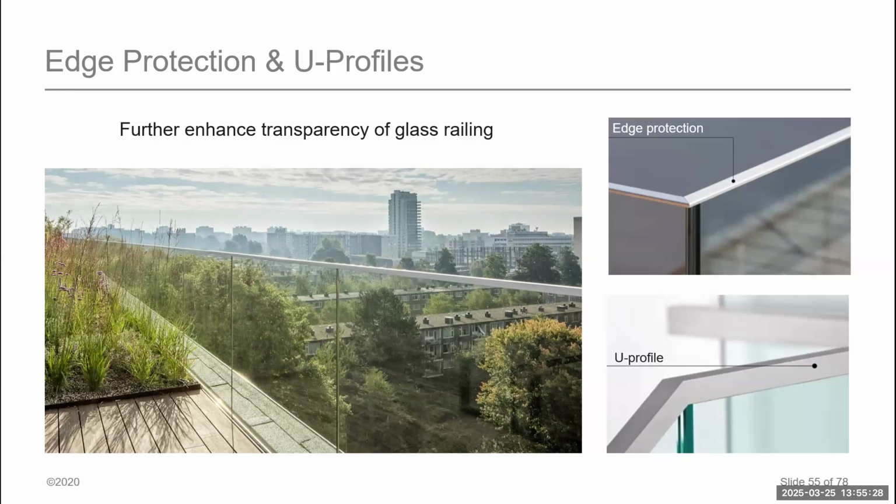The other thing that we also need to take into consideration when we're talking about ASTM and ANSI standards for the production of laminated glass, putting those 2 pieces of laminated glass on a common 48 by 48 inch piece of glass, is that the common slippage allowed by standard is 1/8 of an inch. So you need to take that into consideration as well.